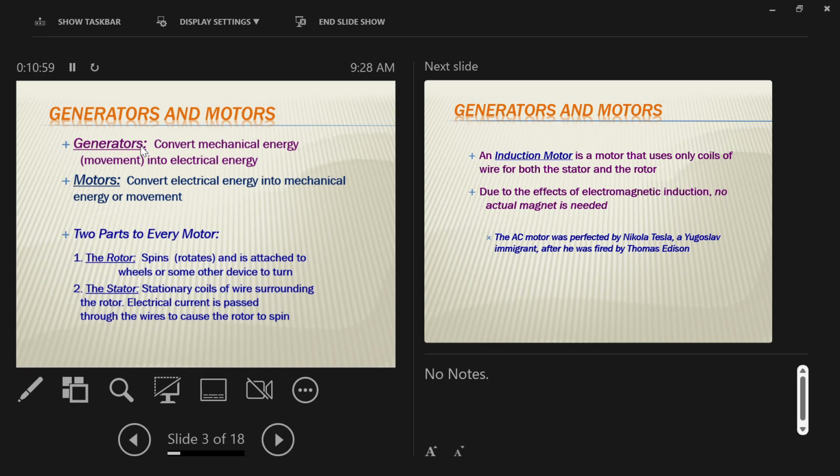It's not captured, okay? In principle, that energy could be captured. So what you have in some electric cars is the AC motor that's used to spin the wheels when you want to put the brakes on the car. So when you apply the brakes on these electric cars, if they have regenerative braking, they can, as you're trying to brake, not use the brake pads to just create waste heat and slow the car down that way, but will actually use the AC motor run in reverse.